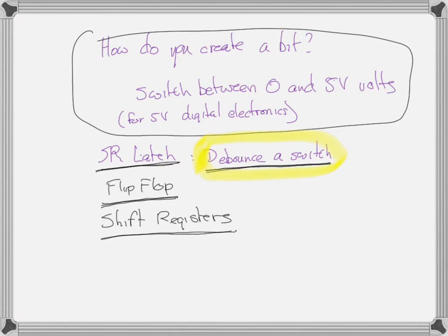So what we're going to do in this lab today is we're going to talk about the SR latch, which is a very, very basic building block of memory. Basically, it remembers its state. You put it in a state and it remembers its state. And we're going to actually use the SR latch to see how we debounce a switch. And then we're going to look at the flip-flop, which is a clocked memory bit. The SR latch is a non-clocked memory bit.